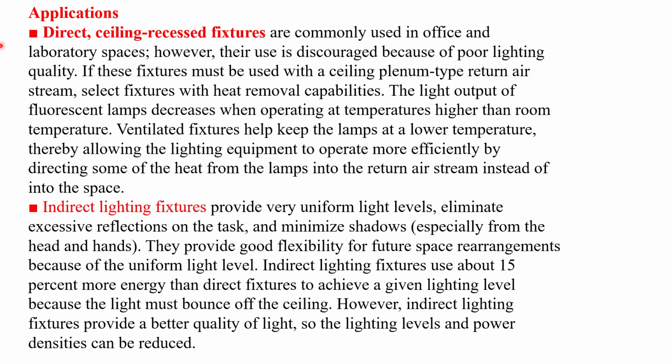Friends, we are now discussing the application of different types of fittings. Direct ceiling recessed fixtures are commonly used in office and laboratory spaces. However, their use is discouraged because of poor lighting quality. If these fixtures must be used with a ceiling plenum type return air stream, select fixtures with heat removal capabilities.